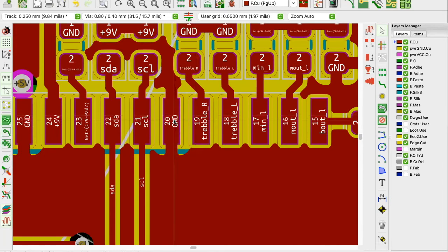If you have solder mask here, it will prevent solder from forming around this edge, because solder doesn't stay on top of it. So it will quickly squeeze to this side or that side. You can see this when soldering boards that have solder mask; the solder will tend to go towards the pads. That's the work of solder mask.